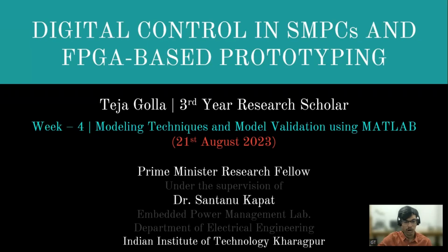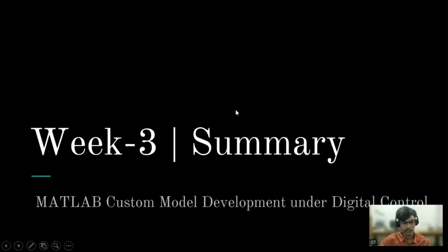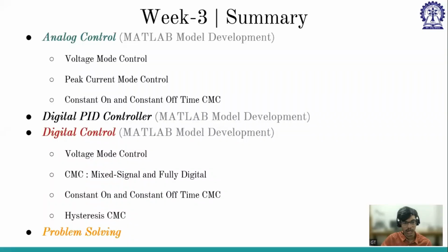So just to summarize what we have discussed in the last week, which is week 3. Week 3 is about MATLAB custom model development and digital control. In week 3, whatever we have discussed was about analog control. So let me select the pen. First I have shown the analog control MATLAB model development. I have shown the live simulations of voltage mode control, then peak current mode control, and constant on time and constant off time, and why minimum on time is required and why minimum off time is required and how to implement them.